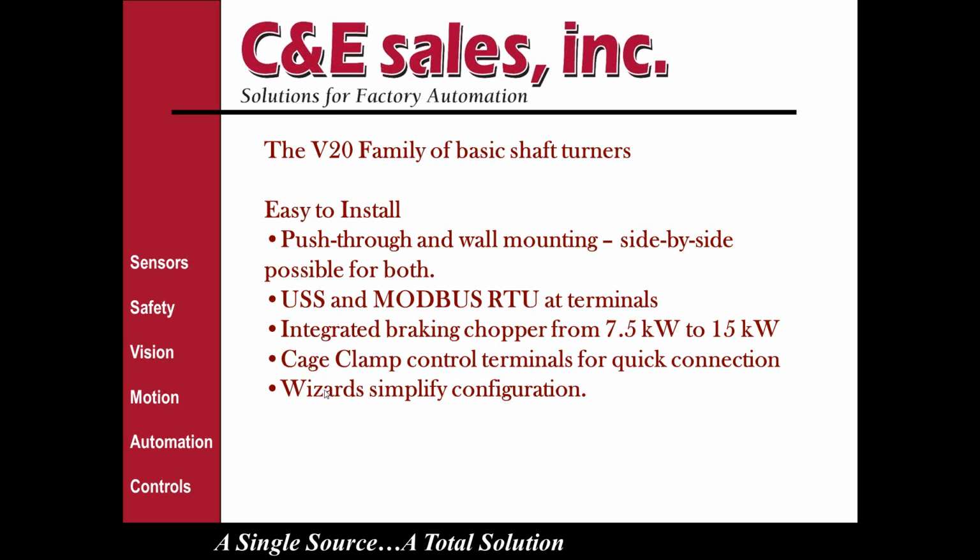A nice feature of the V20 is they have wizards that help simplify the configuration. In the documentation that comes with the drive, they explain wizards for I/O setup and wizards for application setup. By selecting a given wizard, you can very quickly pre-configure the drive to match your application. So if you're doing pump control, there's a standard I/O configuration for that and a standard application configuration. It makes it very quick to set up.